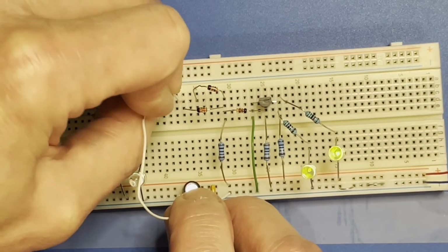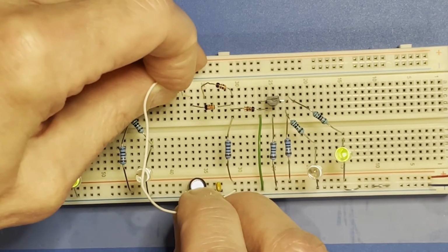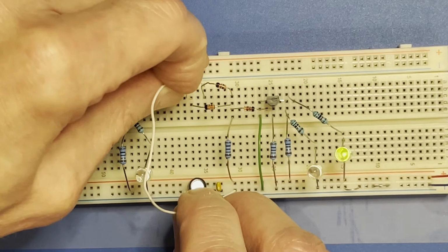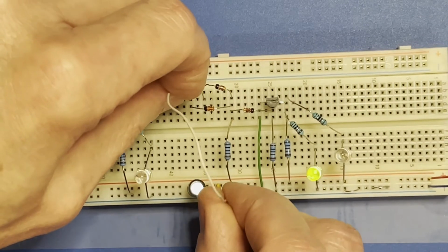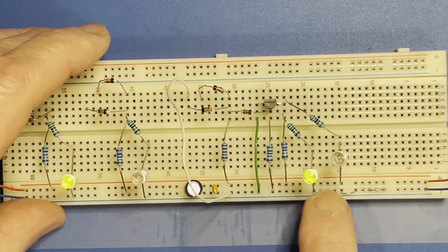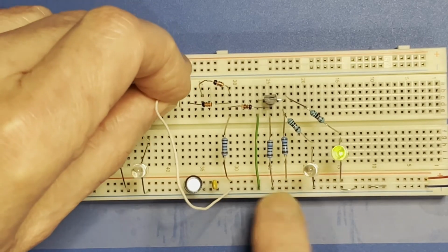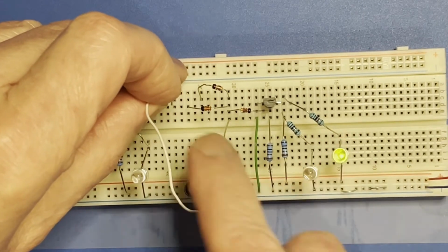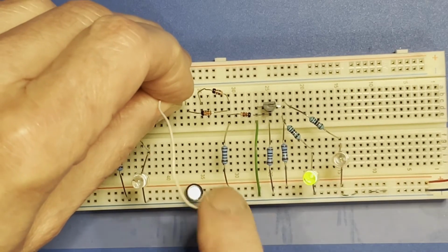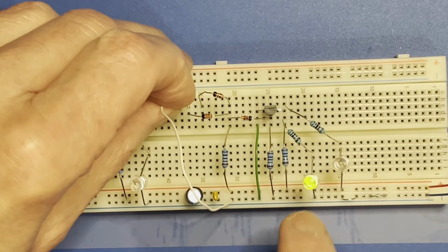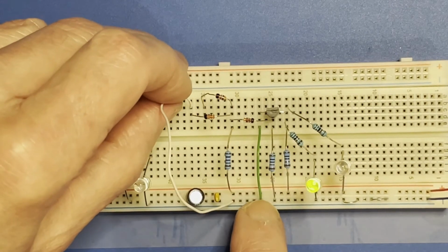So that's the first point. You have to allow for the real world voltages on circuits and how real world components work. And the next point is, well, sorry, there's one more thing. Whilst I'm looking at this, this is a NAND gate. That indicates low. Both inputs are high, that indicates low. And that indicates high. When either input goes low, the output goes high, because it's not AND, it's an AND with an inverted output, or a diode AND with a transistor inverter, literally.